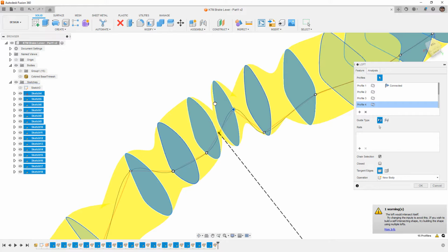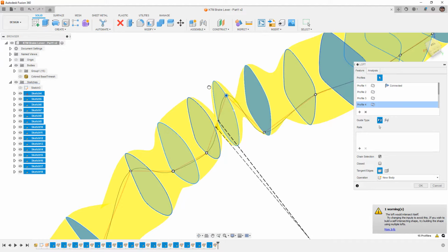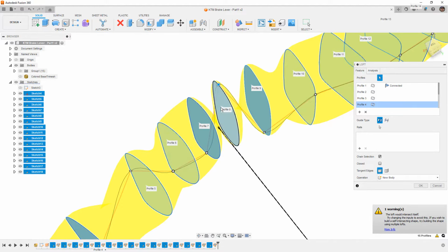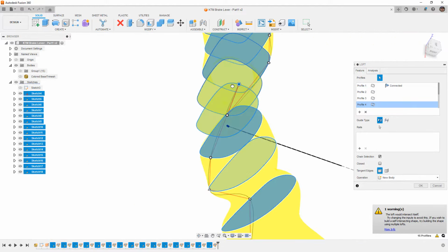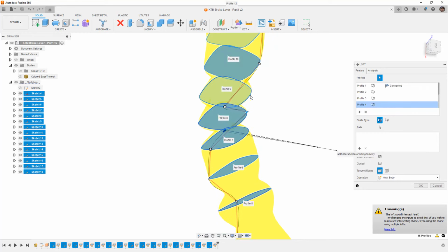Now, because there is a live preview on Loft, it gets a little bit messy. It does kind of hang up because, as far as I know, you can't toggle off the preview for this operation. Some operations you can toggle a preview on, like with mesh tools, you can preview what's happening. With the Loft tools, you are just kind of stuck waiting for it to update. And because what we're doing is essentially breaking the Loft, it's just not working.